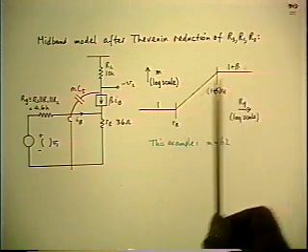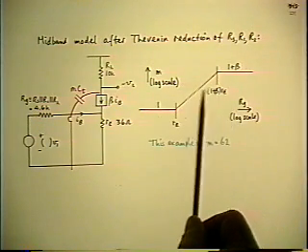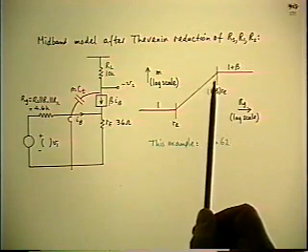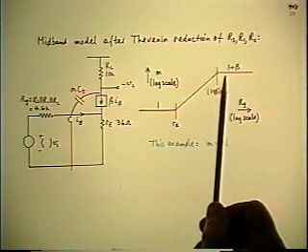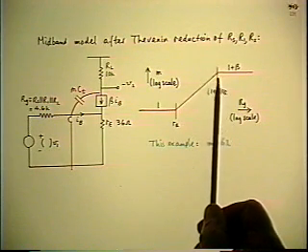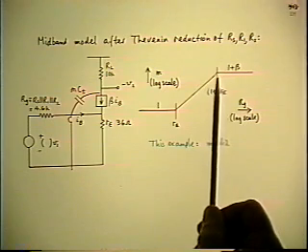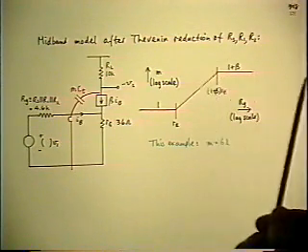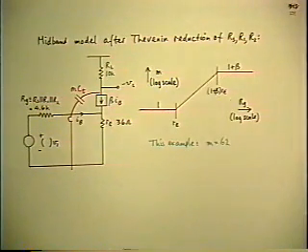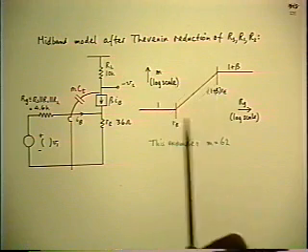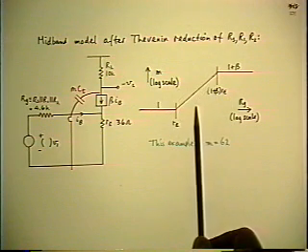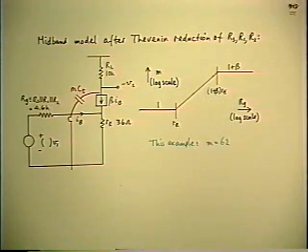Likewise, at the other extreme, if you're not that concerned about bandwidth and you like to use a high RG, what it says is by the time you get to an RG of 1 plus beta RE, the bandwidth is as lousy as it's going to get, and you can make the RG much larger than that and you won't be any worse off. So you see there's a lot of useful interpretation you can get out of that little sketch.